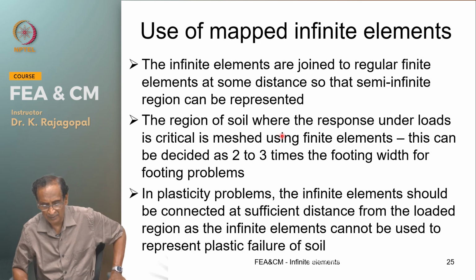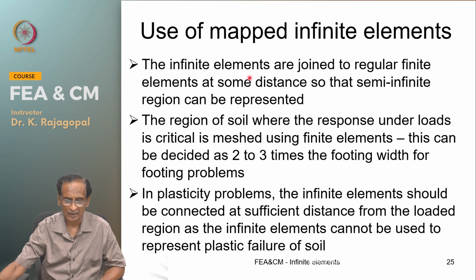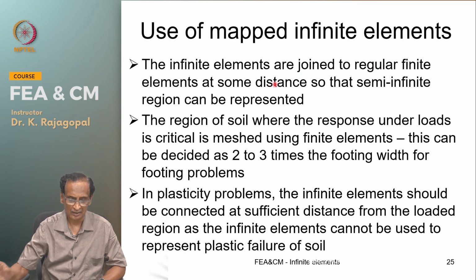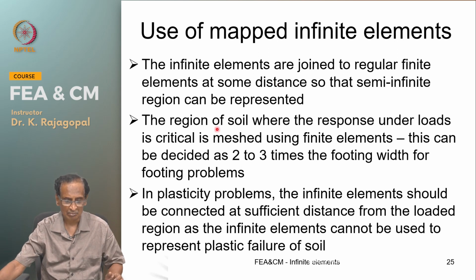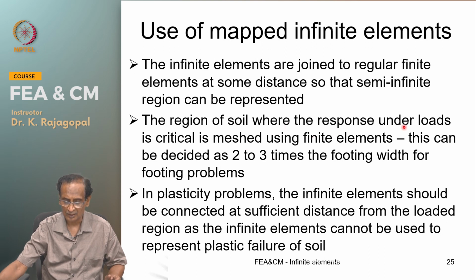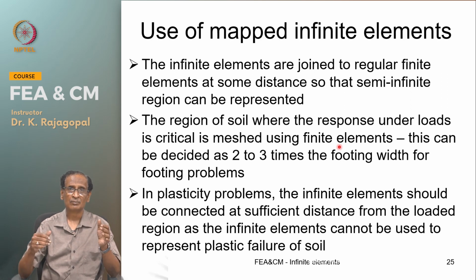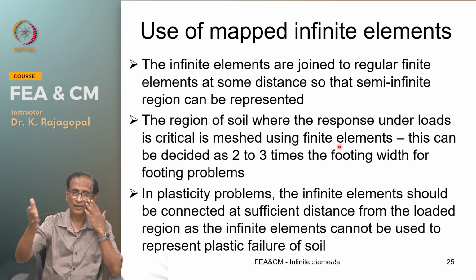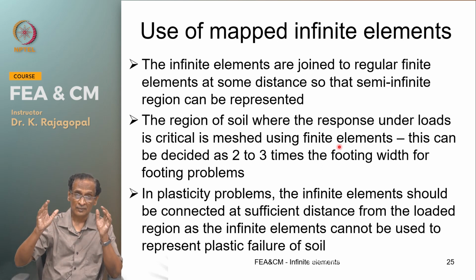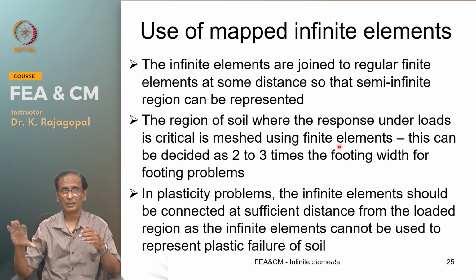So, the use of the mapped infinite elements is very simple. The infinite elements are joined to regular finite elements at some distance, so that the semi-infinite nature of the soil can be represented. The region of the soil where the response under the loads is critical is meshed using finite elements. Normally the predominant influence of any applied load on the surface is felt up to some 2 to 3 times the footing diameter, or say even 5 times the footing size, and within that domain you can have normal finite elements, and beyond that you can place your infinite elements.